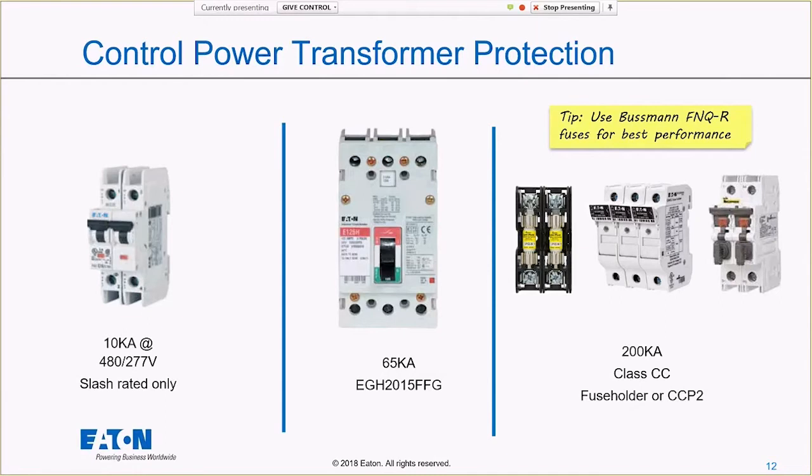And I've had many an example of people who have a lot of power supplies and they use these in front of power supplies, and that kind of just ruins the whole short circuit current rating of the panel. So be aware of that.